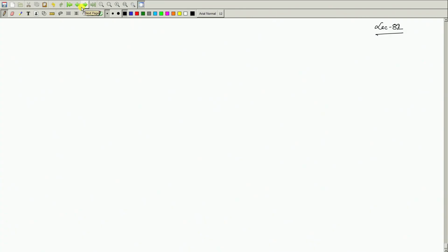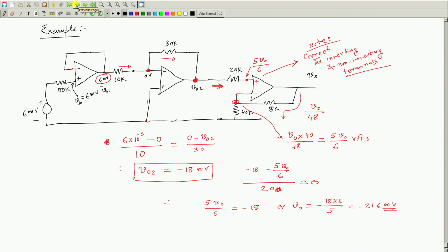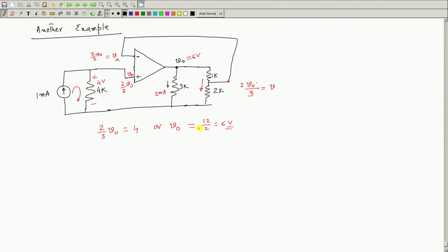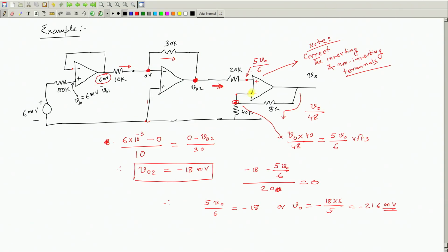And last time, we were telling you about several problems where op amps are used as an inverting amplifier, and inverting amplifier means there must be a negative feedback. While writing down the problems, perhaps in the first place I wrote it opposite. There must be a negative feedback. So, this sign correction, please note that. Calculation part remains same.